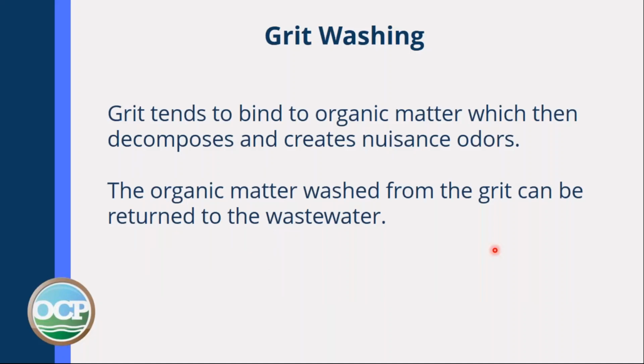Grit, if you collect it before you dump it, it's probably good to wash it, because things stick to each other, and any organic material that sticks to grit will ultimately probably be decomposed by bacteria. Remember, I mentioned the word putrescible earlier, and the result of that is the smell, and people living near your plant may not be very happy with odors that are a nuisance to them. The organic matter can be returned to the wastewater and help feed the plant.